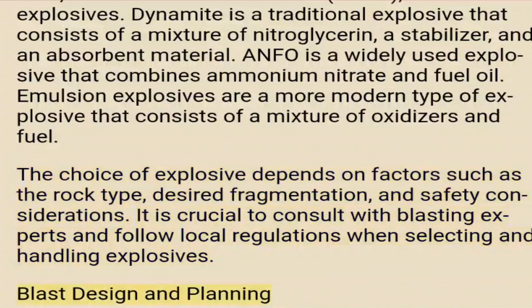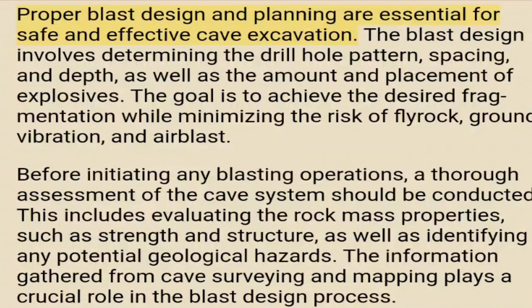Blast design and planning. Proper blast design and planning are essential for safe and effective cave excavation. The blast design involves determining the drill hole pattern, spacing, and depth, as well as the amount and placement of explosives. The goal is to achieve the desired fragmentation while minimizing the risk of fly rock, ground vibration, and air blast. Before initiating any blasting operations, a thorough assessment of the cave system should be conducted. This includes evaluating the rock mass properties, such as strength and structure, as well as identifying any potential geological hazards. The information gathered from cave surveying and mapping plays a crucial role in the blast design process.